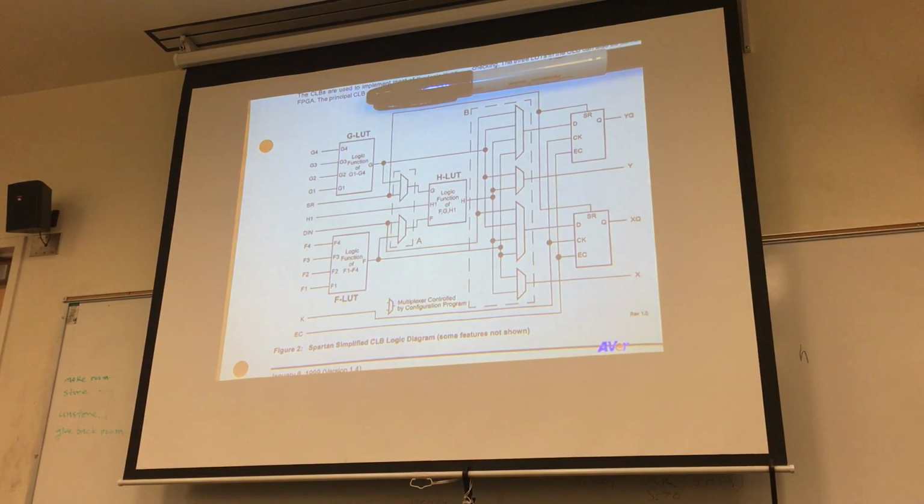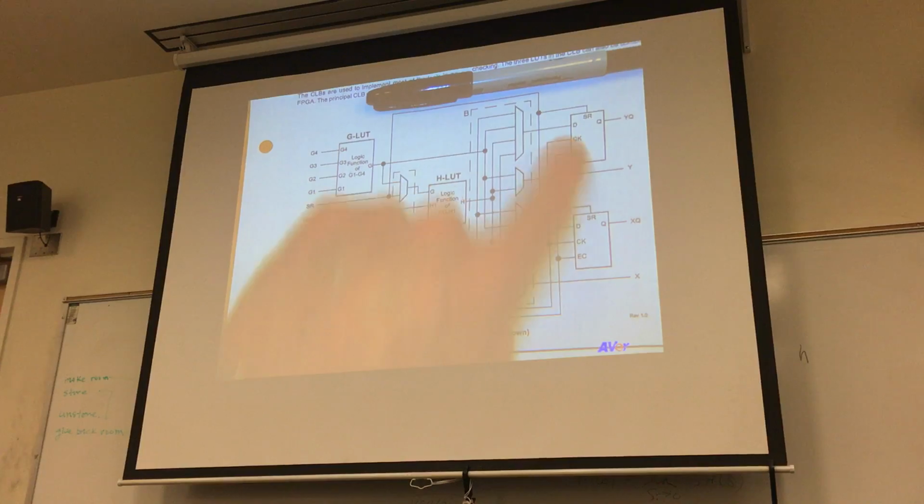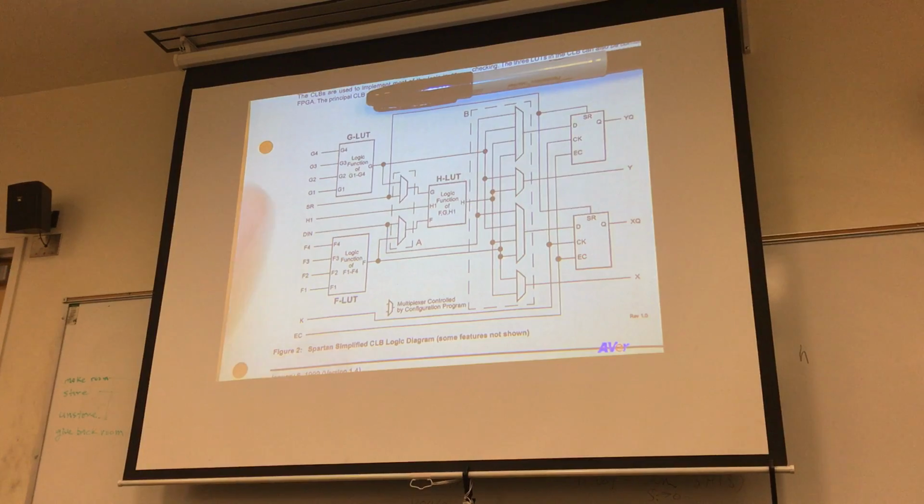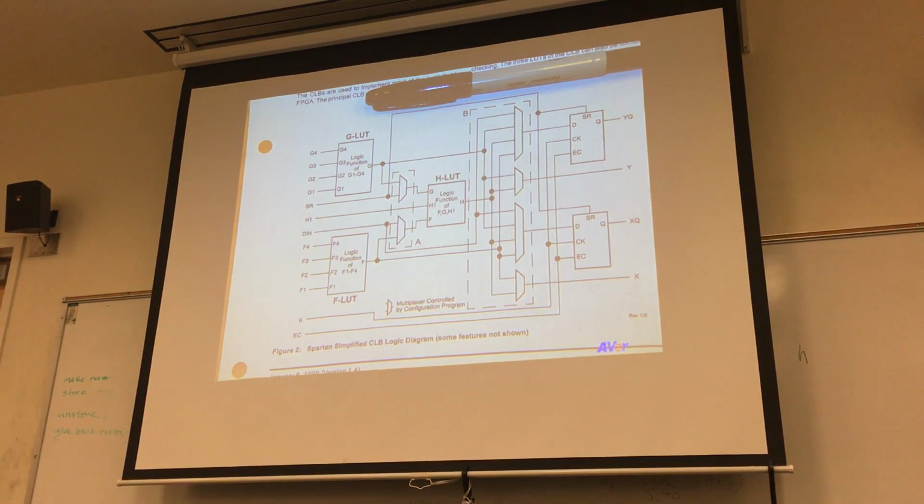So when I talk about programming the configurable logic block functionality, what I'm talking about is initializing the memory location contents in the LUTs, and we're going to look at some of the circuitry here. It's a little more flexible than what's shown in this simplified diagram. Every configurable logic block looks like that. So there's not really any gates in the configurable logic block.